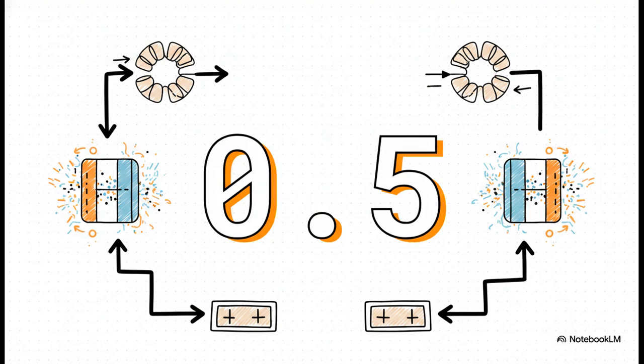And here is the real payoff. The formula for stored magnetic energy. W equals 1/2 L i squared. This shows us exactly how a magnetic circuit acts like a temporary, measurable battery. When we push current into the coils, we are doing physical work to establish that magnetic field, and that energy is stored in the magnetic circuit. And get this, it's largely stored in the air gap itself. Then, when the field collapses, all that energy is handed right back to the electrical circuit. This exact transient storage mechanism is what makes AC motors and transformers even possible.